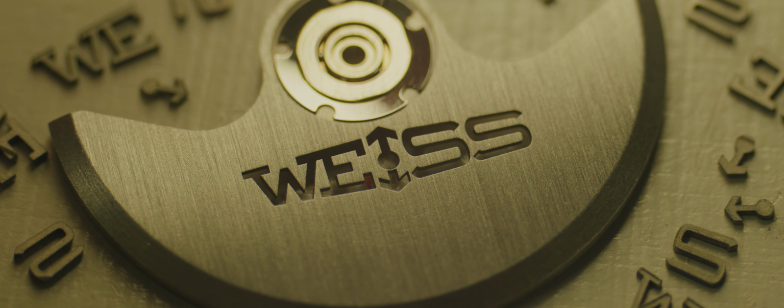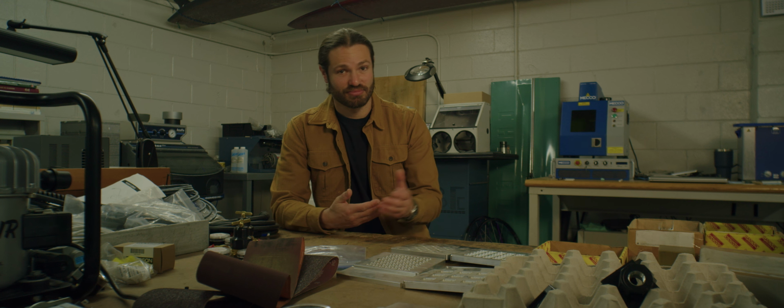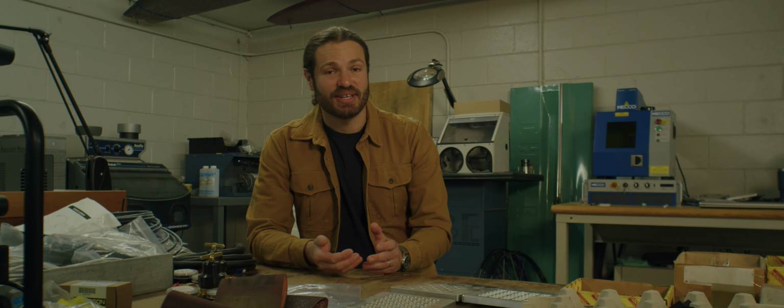also laser marking. Laser marking allows me to cut or mark on metal in a way that I couldn't do with an engraving tool, because a laser does not actually have any dimension. So using a laser for cutting or engraving allows me to have sharp internal corners. If I was to use a 3-dimensional engraving tool, I have to leave some space for the tool. So there will be a radius on an internal corner, and it cannot be a true corner. With the laser, that's possible.